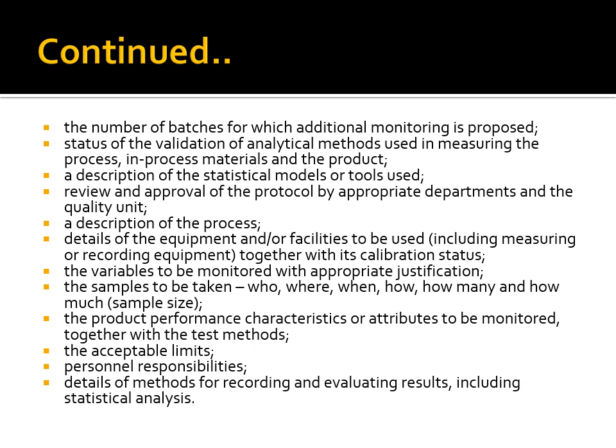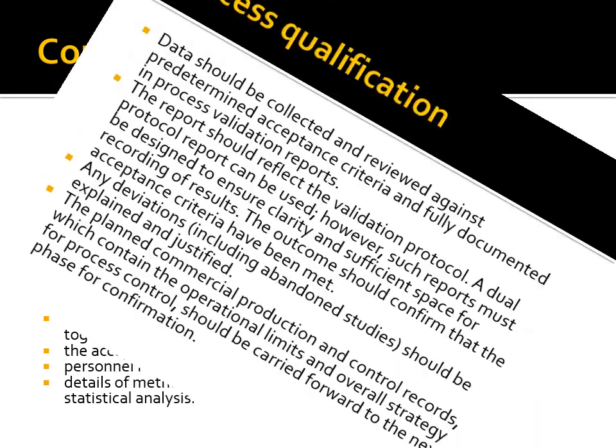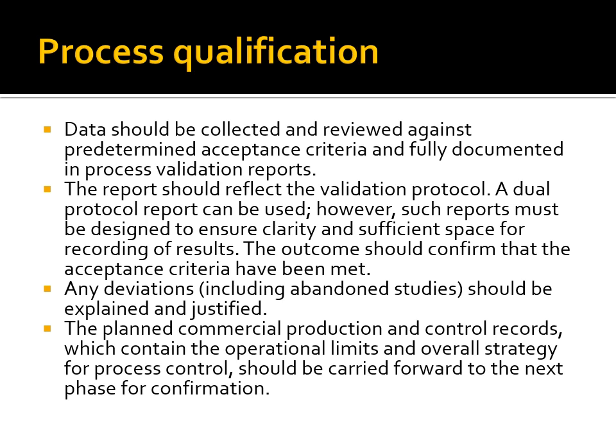to be monitored, together with the test methods, the acceptable limits, personnel responsibilities, details of methods for recording and evaluating results, including statistical analysis. Data should be collected and reviewed against predetermined acceptance criteria and fully documented in process validation reports. The report should reflect the validation protocol.